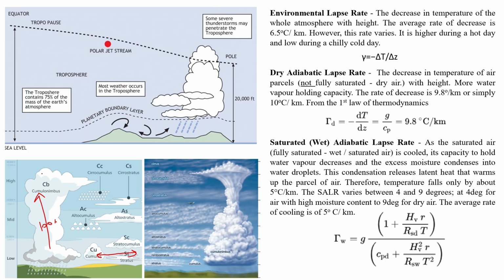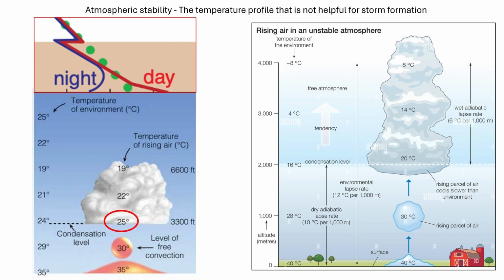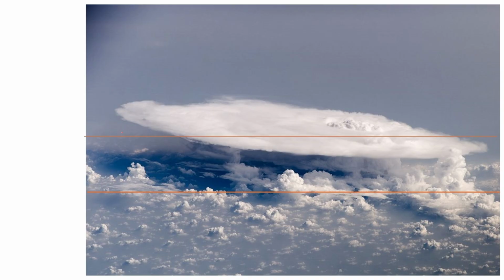This cloud also, once it reaches, for example, up to this, here temperature is high, here temperature is less, so it keeps on rising. Once the temperature is equal to the outside temperature, then it cannot climb further, so it will spread within that layer itself, so that we are getting the flat annular kind of shapes you can see here. So this may be the entrainment zone or inversion zone.